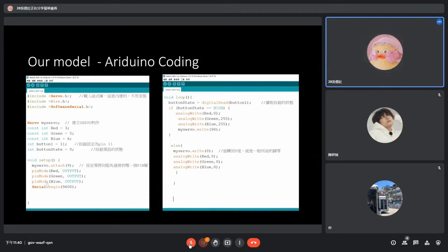Introduction to the program. Use the signal of the button to simulate an earthquake. When receiving an earthquake signal, turn on the servo motor, turn 90 degrees, and change the light to red. If no analog earthquake signal is received, the servo motor stays at the 0 degrees position and the light stays white. Next, please introduce our finished products in detail.